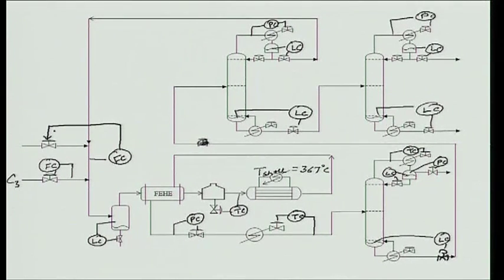So, I have taken care of that. Now, let us start doing some stuff. I am going to set the reflux in ratio with the feed to the column. Okay. So, I take the reflux, the feed, I multiply it by the set point, and this is going to set the reflux into the column. This is a set. Okay. Then I need to control, of course, the inventory of propylene dropping down, which is controlled by doing this.